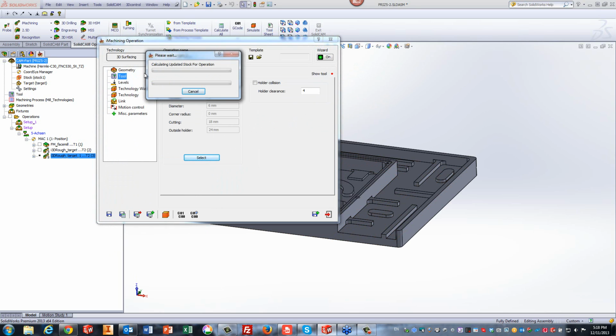Now, because it looks in our geometry area, it will machine only areas that were not machined before. It'll only work in the areas where it needs to work. Now, again, you have all of these depths over here, which I did not have to deal with. It was done automatically. The calculation will be finished momentarily. Now remember, it's actually calculating every single one of those levels. So the calculation does take a little more time, but we're just about finished now.